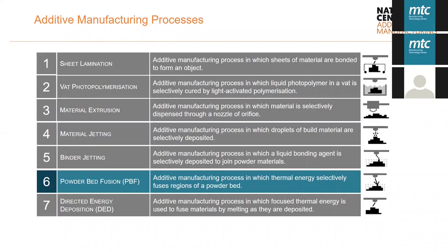So how can metal binder jetting be used for manufacturing an orthopedic implant from, is it Ti6Al4V? Yeah, so Ti64. Using Ti64 material in metal binder jetting or any indirect additive process, as far as I know, is quite difficult, mainly because of potential oxidation of that material. It's very reactive, so it's quite difficult to manufacture using indirect additive AM processes, mainly because there isn't a reduced environment in the processing itself, or sometimes the debinding.